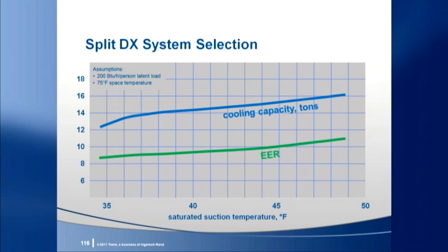If the coil is selected at low suction, then hot gas bypass will be required to operate sooner to try to stabilize the coil temperature. Remembering that hot gas bypass is not an efficient way to unload, it's easy to see that a system selected at higher suctions that doesn't so quickly need hot gas bypass to operate will use less energy. Having said this, we can understand the value of a packaged unit where selection and testing of the reheat, hot gas bypass, and cooling coil have been done by the manufacturer.